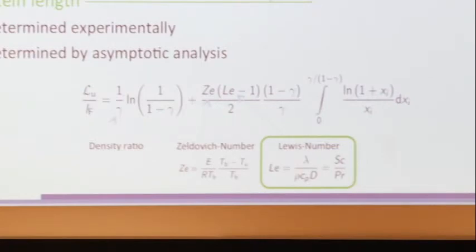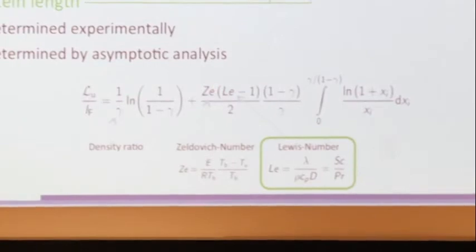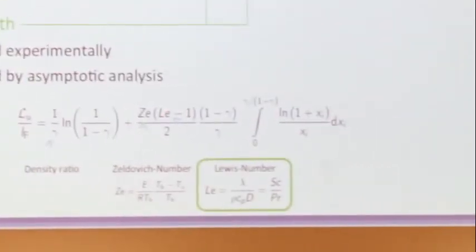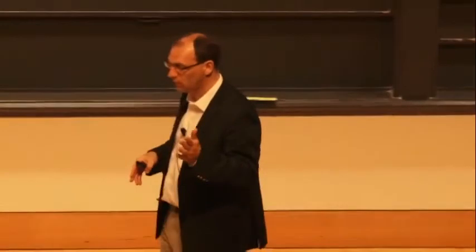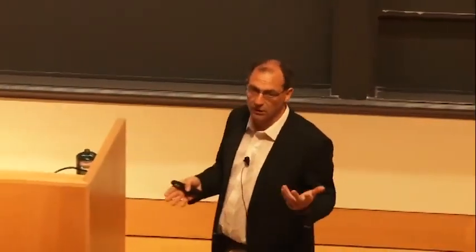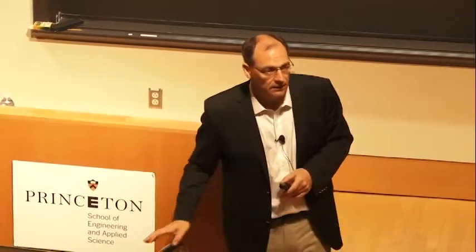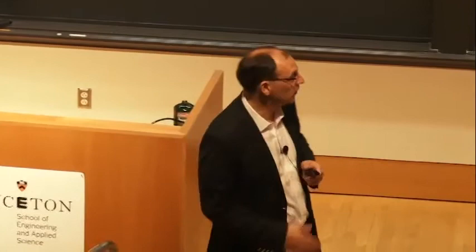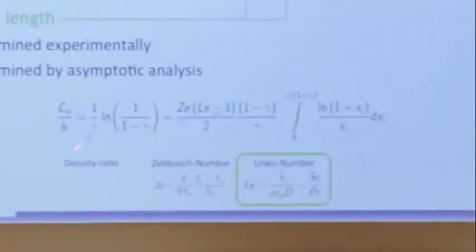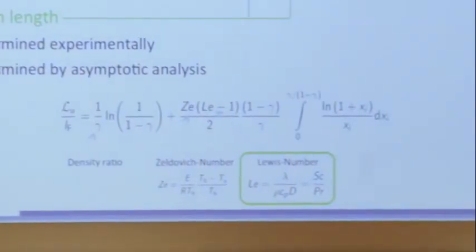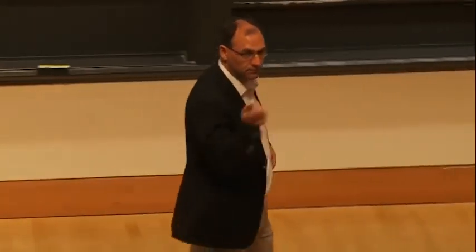It's characterized by this term, and chemistry characterized by this term. Interesting here also is that you see that the Lewis number can be smaller than 1. For example, hydrogen has a Lewis number of about 0.3, very small. Or it can be larger than 1. Typical larger hydrocarbons like heptane have Lewis numbers larger than 1, could be 2 or so. And so you could see this can be positive or negative, and depending on what this is, also the Markstein number or the Markstein length can be positive or negative. Okay? That is important.